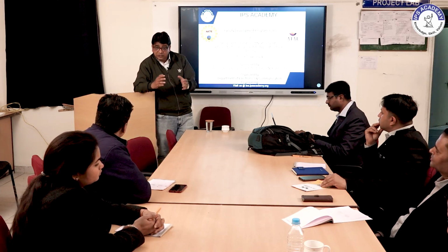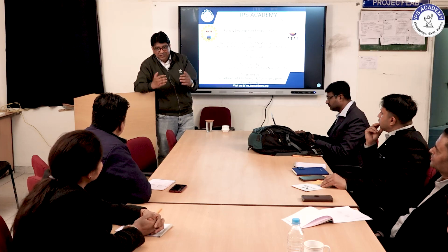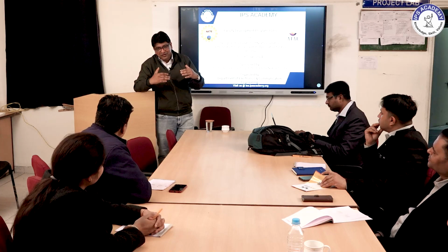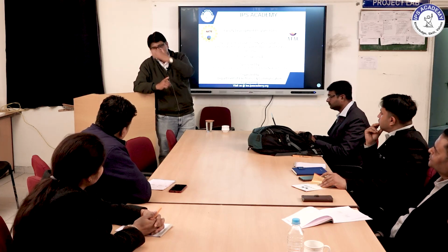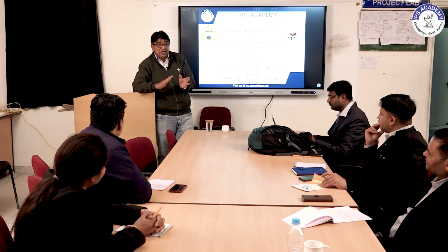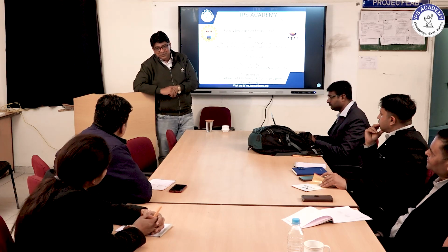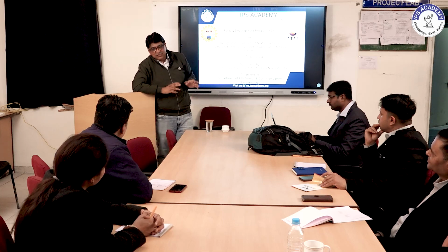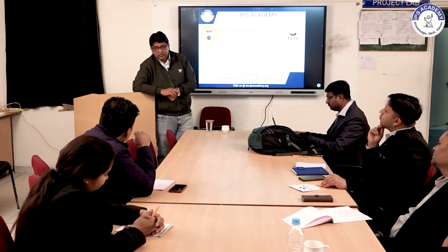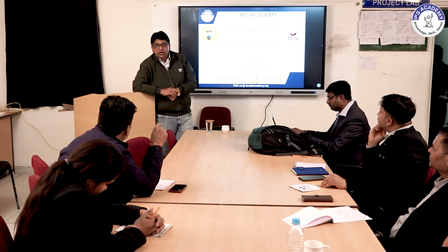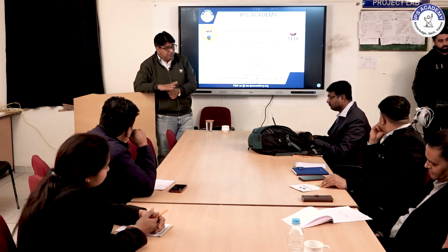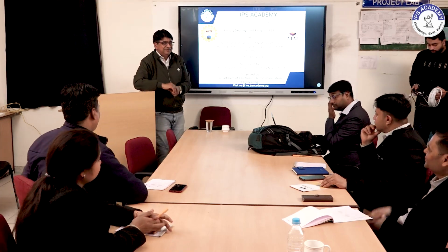And sometimes it goes more than the channel length, and then another short channel effect, punch through, will be there. When both barriers touch each other, electrons will pass at very high speed. So we have to avoid this punch through, but somewhere it is advantageous. I am discussing here from the biosensing application point of view and circuit aspect. So in punch through, I think the device behavior is linear after that. Electrons will pass at very high speed, and might be linear, sir. Okay, ma'am. Thank you very much.